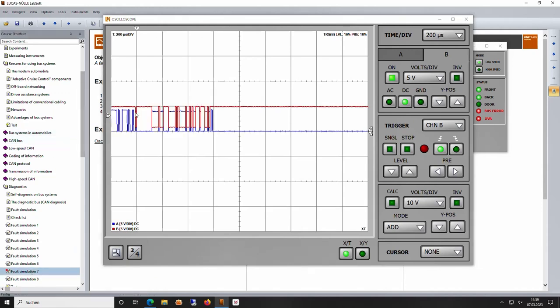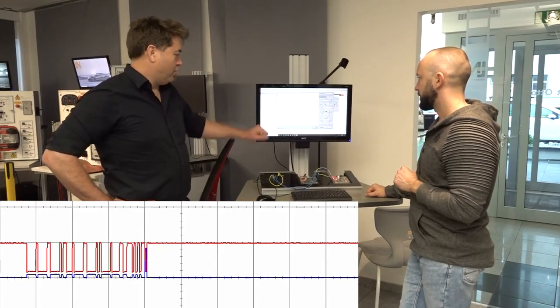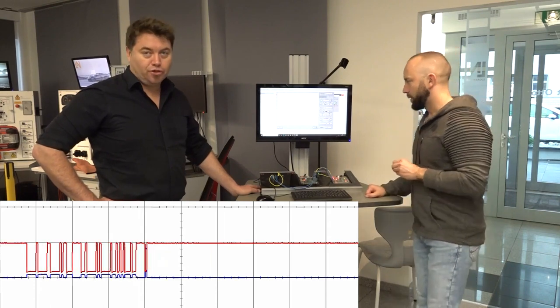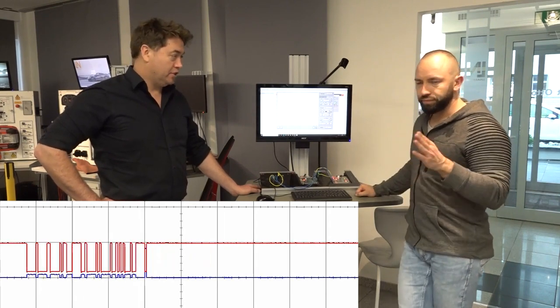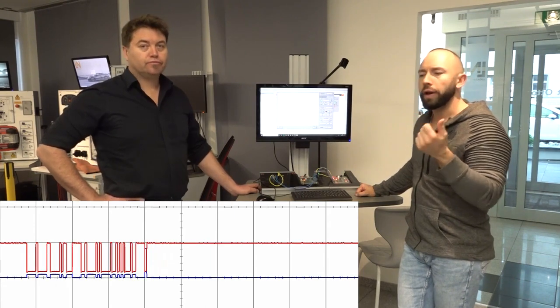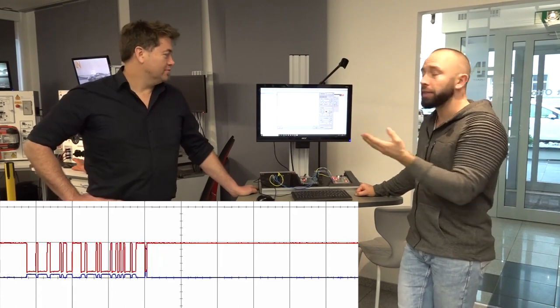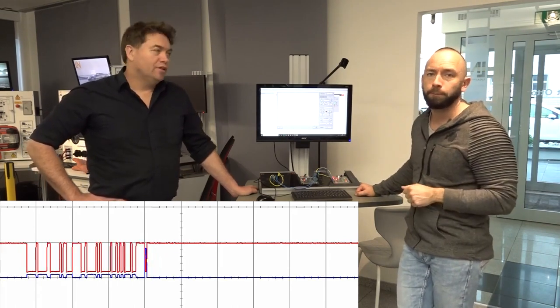And this is now showing the same fault on the different side, the CAN low side. And this one here, to finish up, I think it's pretty obvious to see there's a high resistance on the CAN high signal as well. That can easily be created by corroded connectors or whatever, something in that range basically. So you will find that on older cars obviously.